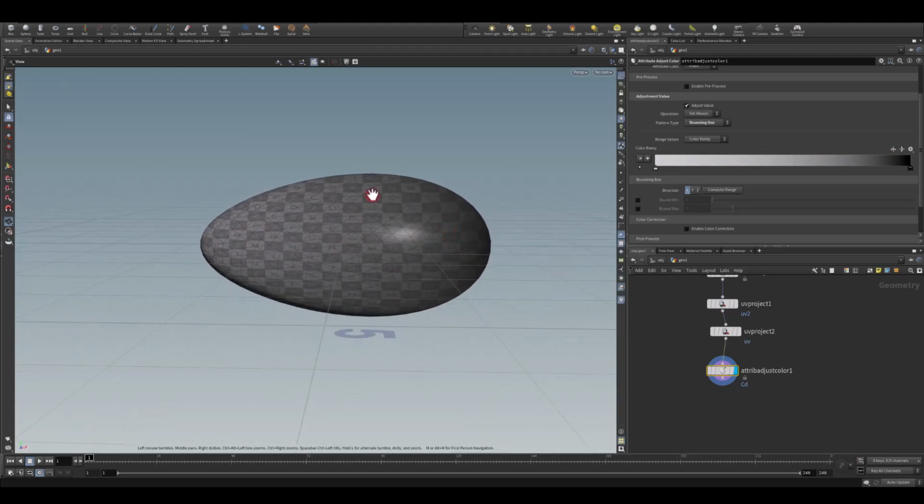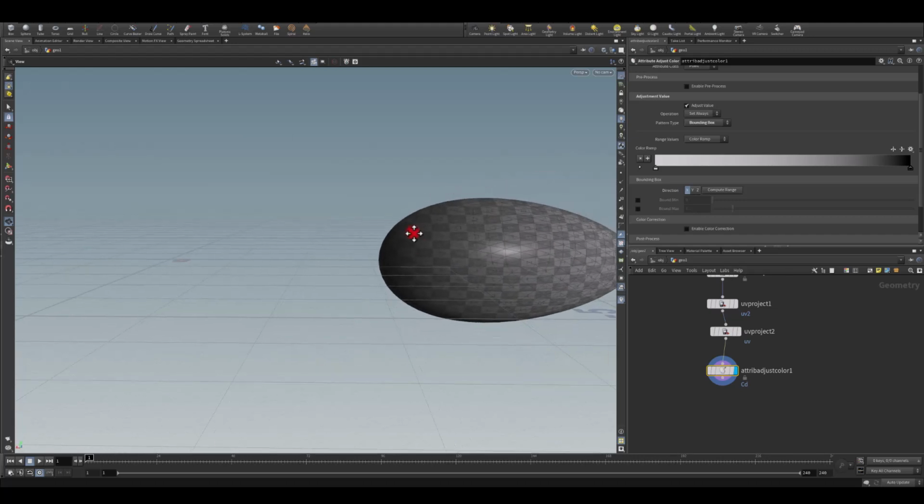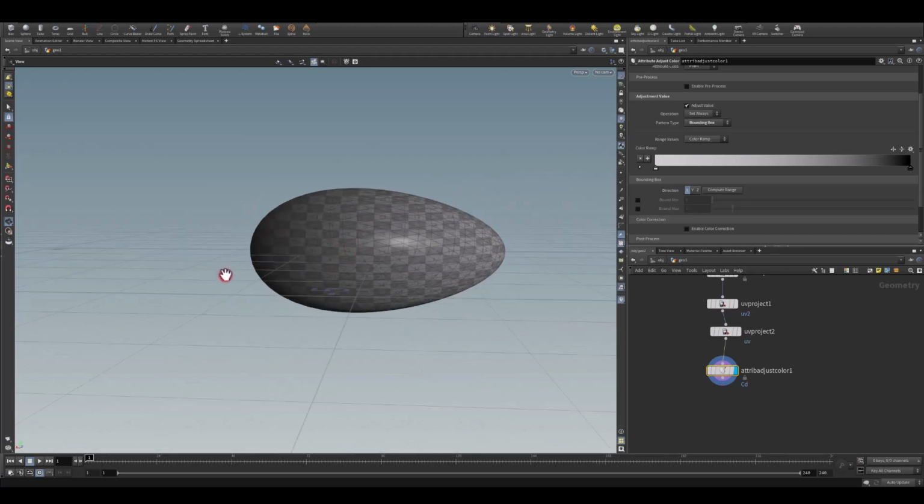game engine. It's got this gradient, so I can control the vertex color using the power node in the material editor in the game engine. And I can control where I want this to be. Ideally, for example, if that's our front, I can use it for a glow at the beginning of the projectile, or if that's our back, I can maybe use this for an alpha to get rid of transparency from, actually add transparency here.